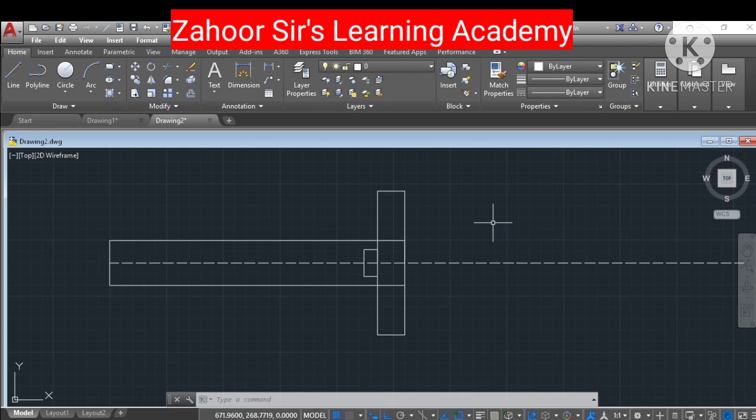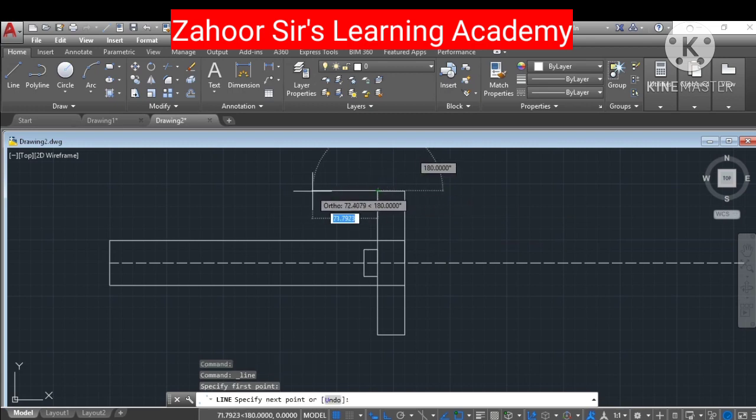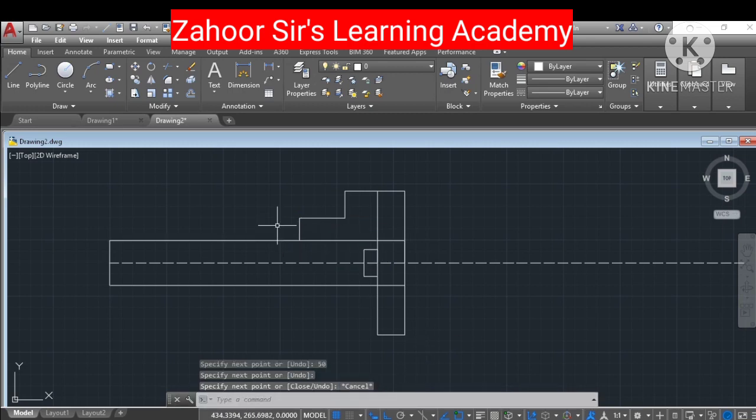Now I will draw the flange part of it. To draw the flange part, I'll go to the line command again to pick a line. From this point, I'll go to the left. That left I have to go to 36 mm, then press enter. Then to show the flange part, I'll go 30 mm down, then enter. Now I need to go 50 mm this end, then I need to go down 25 mm, then escape the command. So this is how I have done it.